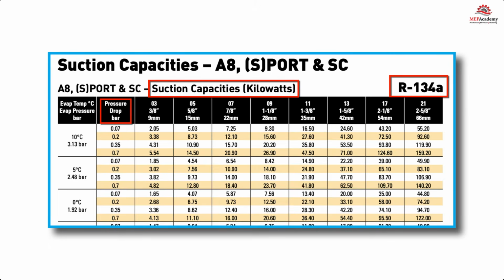When choosing solenoid valves for refrigerant system, the engineer will use the refrigerant type, the tonnage, and the maximum operating pressure differential as the selection criteria. Manufacturers provide tables for selection of their solenoid valves.